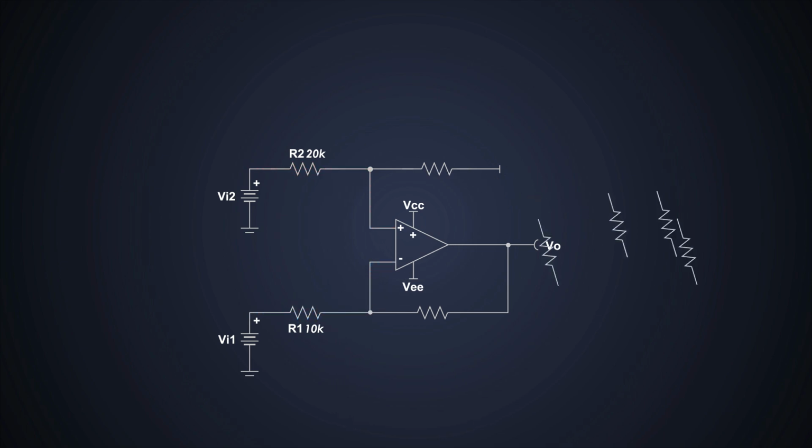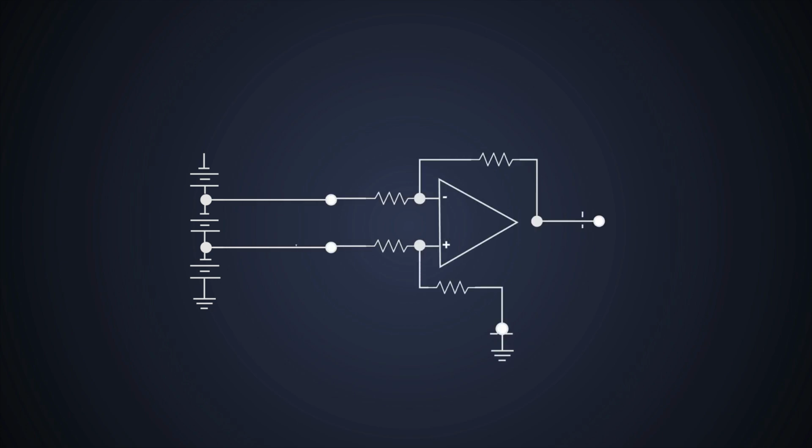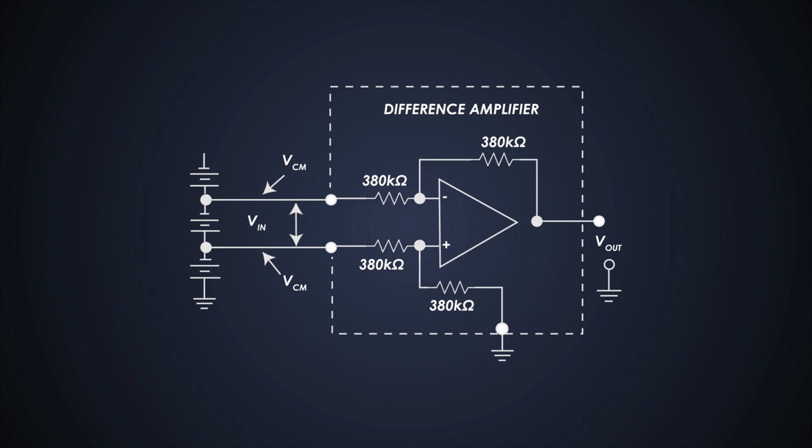Also, this circuit requires a very close ratio match between these resistor pairs. Otherwise, the gain from each input would be different, which again affects the common mode rejection. For example, at a gain of 1, with all resistors of equal value, a 0.1% mismatch in just one resistor will degrade the CMR to a significant level. In spite of these problems, this difference amplifier is very useful in applications such as battery cell measurement, where DC common mode voltage may be greater than the supply voltage.